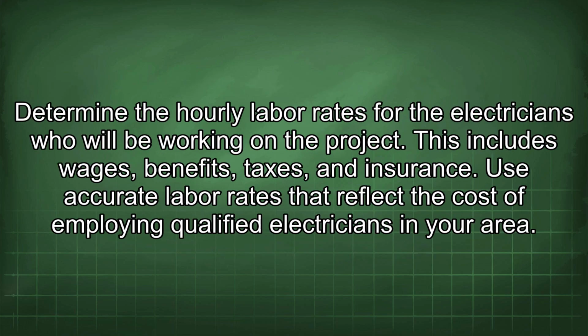Sixthly, calculate labor rates. Determine the hourly labor rates for the electricians who will be working on the project. This includes wages, benefits, taxes, and insurance. Use accurate labor rates that reflect the cost of employing qualified electricians in your area.